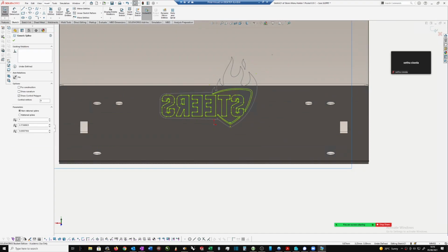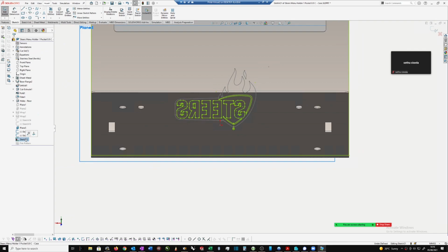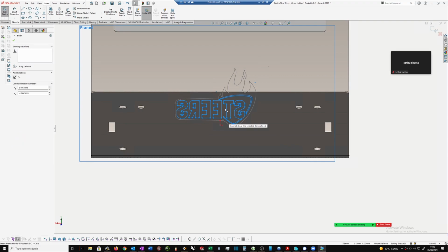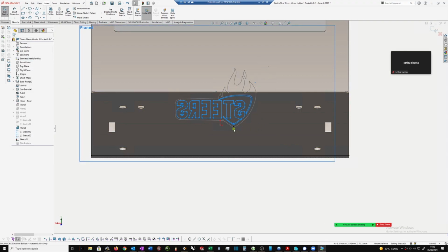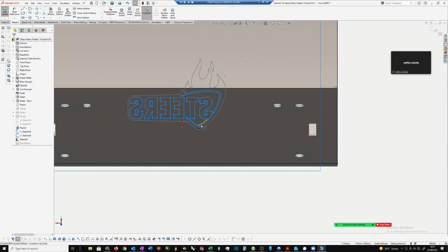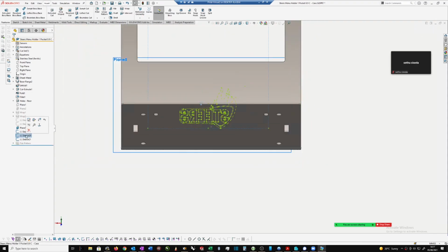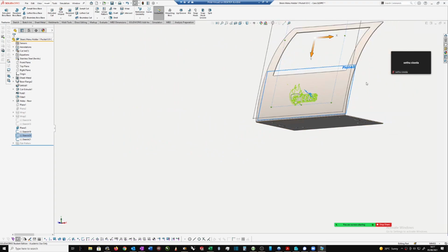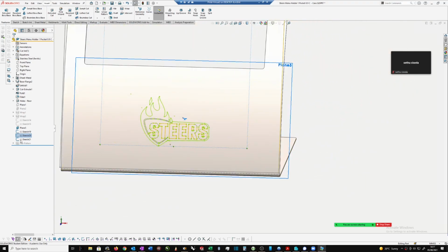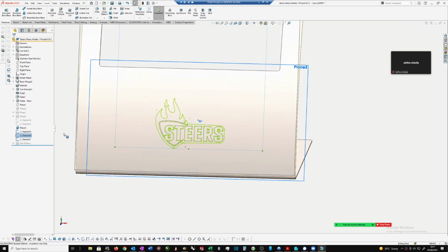So if I grab, is it going to do it? No, it's not doing it, because that's linked. All right. Okay, so if this little point wasn't linked, I could grab a part of the sketch and move the whole sketch around. So let's exit this one, because we've done enough on that one, and we go back to this sketch. So this might look a little bit confusing. Let me just make sure that it's not too confusing. There's my bottom sketch. It has everything in it, and then this top sketch, or the second sketch, only has the logo with these two swishes.